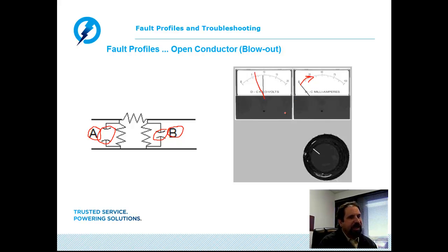Now, if we are thumping onto the cable, another thing to watch for in the case of a possible burn back condition is when the thumper discharges. Instead of getting a sharp kick or drop in volts and a strong kick forward in current, watch your meters. What may happen is you get just a very slight kickback on your voltmeter and just a very weak kick forward. This basically is telling you that the gap is very large. It's taking a lot of energy to drive that arc across it.